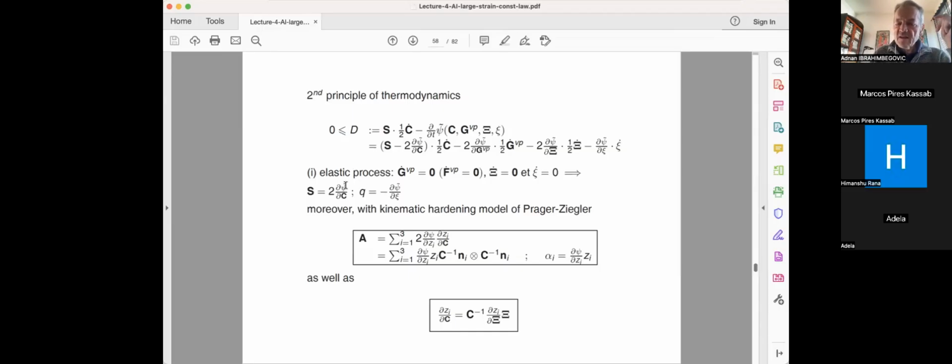second Piola-Kirchhoff stress is the derivative of such a potential with respect to the Green-Lagrange strain, or 2 times the derivative with respect to the Cauchy-Green right deformation tensor. And I also introduced the conjugate variable to a hardening variable. Little q is equal to the derivative of this potential with respect to a lowercase psi, isotropic hardening. And of course, I can introduce the conjugate stress, which is called back stress, to the hardening strain for the kinematic hardening, which is uppercase psi.